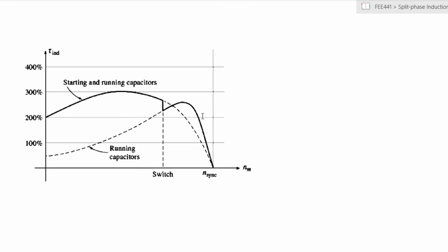And in this case, you will see that you have a torque speed characteristic that looks like that. What we'll notice is that this kind of configuration gives us across the board the most balanced level of torque. You will notice that the torque for the majority of the operation, whether it is running or starting, is within the same range from 200 to 300%. There are no wild variations. So this particular type of configuration gives us uniform or regular torque.